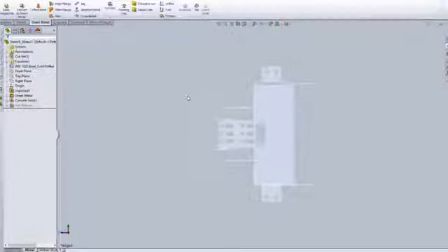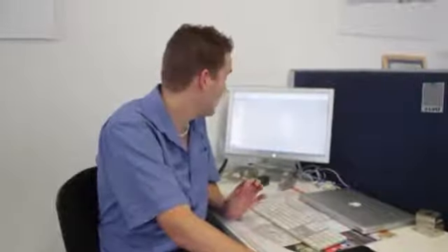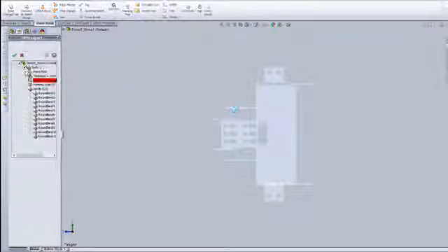So today we've got a 3D part that we've been sent from a customer, and we've got it open here in SolidWorks. So I'll go through the various steps and we can send it down to the machine. We're going to use a great tool from LVD called OSM, which is Open Sheet Metal. What that does is it automatically saves the part in our database for our Cadman B software. This is our bending software, so then we can go through and test bend it. All we have to do is use our OSM export and export the part.